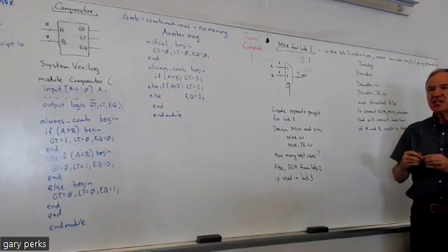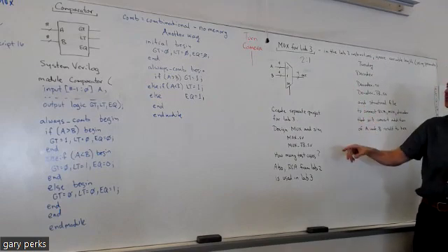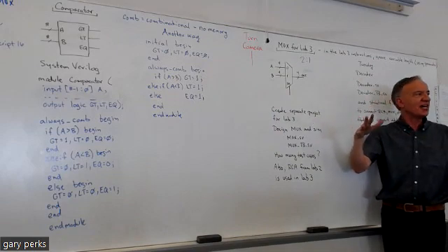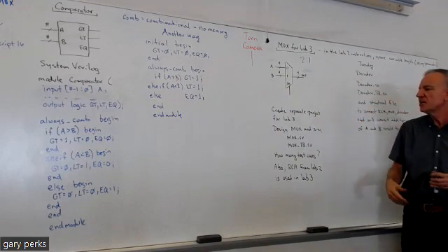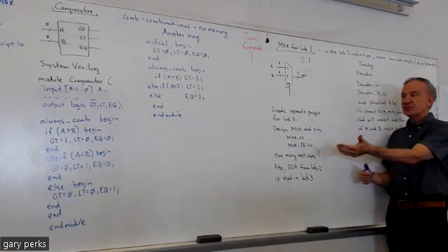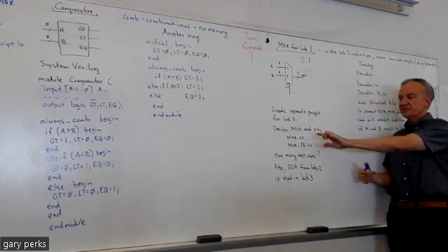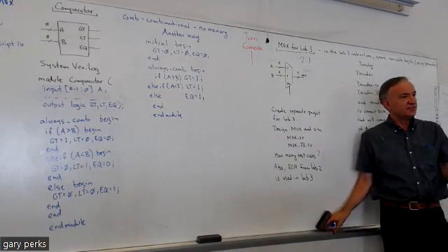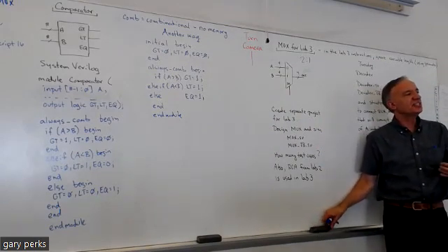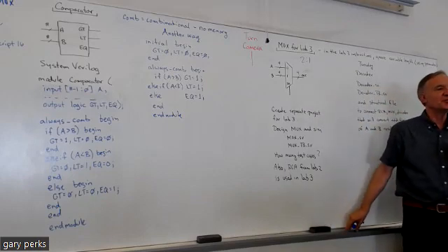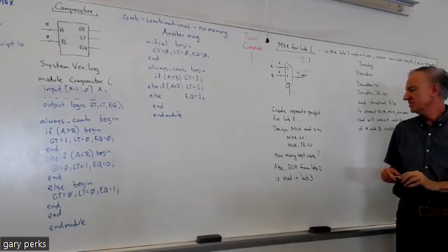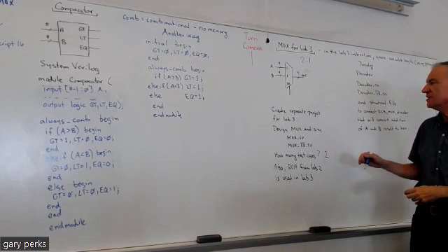So what you can do today, after you finish the activity, is create a separate project for lab 3. Hopefully you've been doing that for all the labs, like I suggested at the beginning of the quarter. And then just do a design source that has the if statement for this 2-to-1 mux. Then you'll need a sim file. How many test cases are you going to need to make sure that this 2-to-1 mux is working the way it should? What's the minimum number of tests? Yeah, 2. You just need 2 test cases, right?